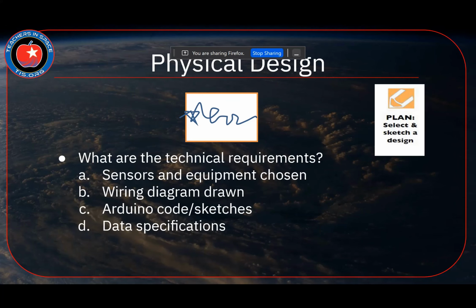Then once you have all of that, you're now going to start getting physical. You're going to think about what the technical requirements are for this logical design to be put into practice. So what are the sensors and the Arduino boards and the equipment that we're going to be using at that point? You're going to want to have a wiring diagram drawn up, similar to what I was showing you guys in the workshop. The program that I use is called Fritzing, and I will add that to the slideshow with a link.